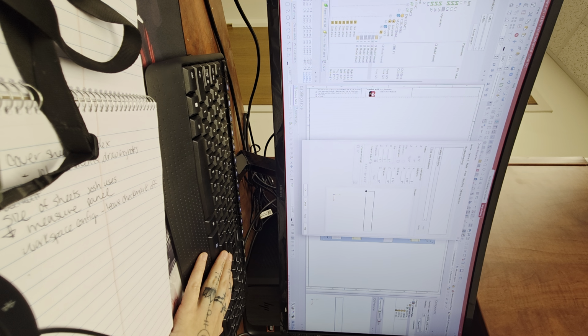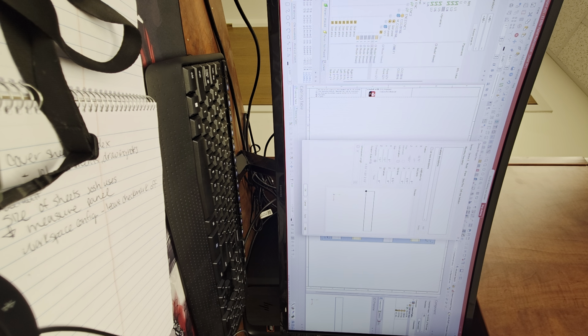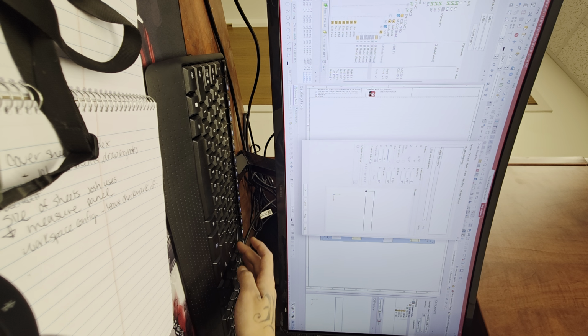Right click, device properties. So here on the left side, where you have your X and size, Y, and Z for that matter. So for Y being 1.5 inches, one just below that. They're right there. Right, so 1.5 is our current height and width of these ducts. Now, considering you're not using either the height or width of these, I would set them to 0.1, both for height and the width itself, because you really don't want any interference in your layout at all. From a duct perspective, you want them to be as least impactful as possible. While the length is okay, length can be 8 inches, that's all right. And then click apply and OK.